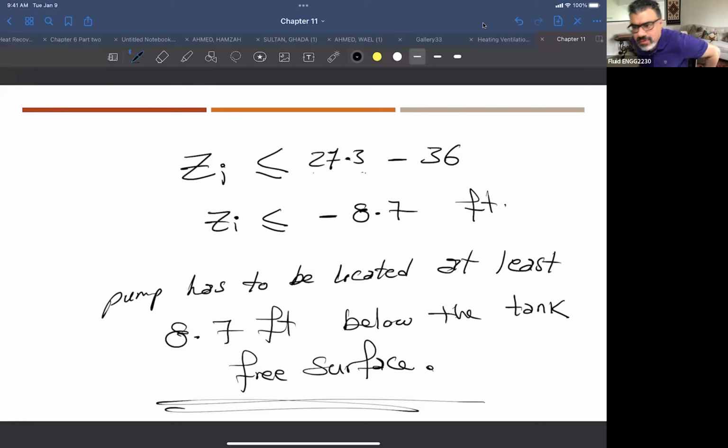choose a different kind of pump if cavitation will happen. Like, sometimes as an engineer, you have a certain condition for this tank. Imagine you are lifting from a well. So the well is down. So the level of the water is down. So now you want to put the pump up, right? So now you're going to put pipe going down and then you are sucking this fluid. So it has to be a different type of pump. Yes, it's not a centrifugal pump, a hydrodynamic pump working differently.